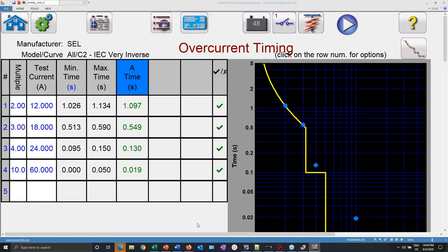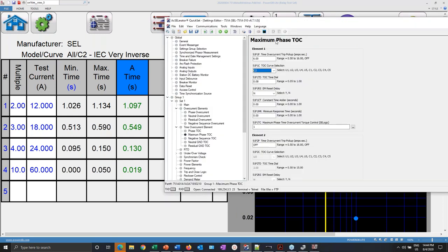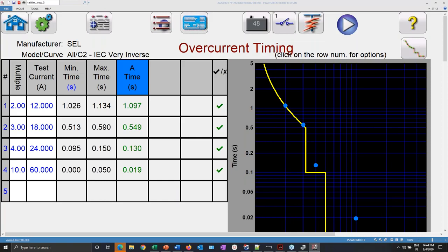And I have it automated. No matter what changes happen on the relay with those elements that I have right there, I can always read the setting and I can run the test, and I don't have to worry about, oh, did I configure the test right? Did I configure the test wrong? Did I do something right? Did I do something wrong? I could even configure other types of elements following the same, let's say, procedure.